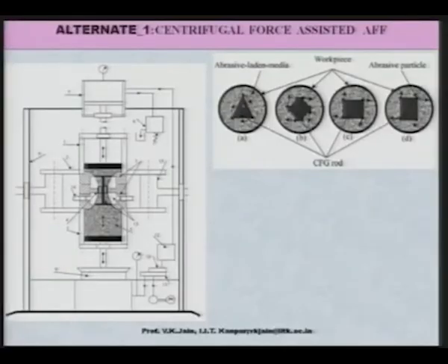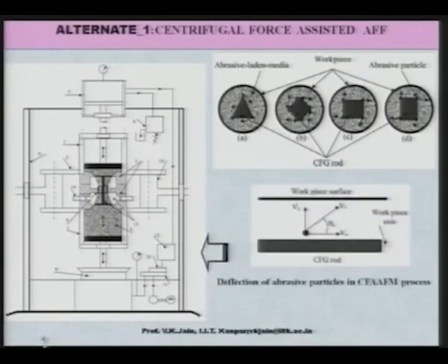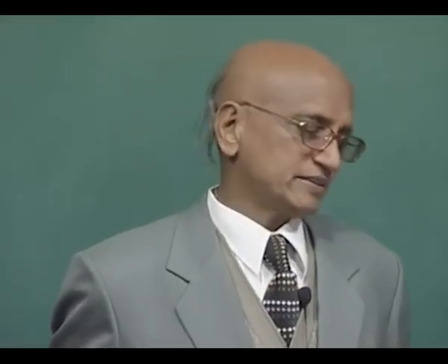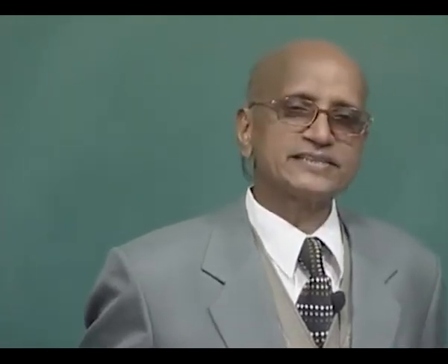Now, these are the 4 different shapes they have attempted with, and they claim that the finishing rate improved when they used these kinds of rods as compared to the case when there was no finishing rod. And they gave some analysis also, and they have tried to prove that higher force is acting, and because of higher force penetration is also higher, and they did not give any analysis related to the cutting force.